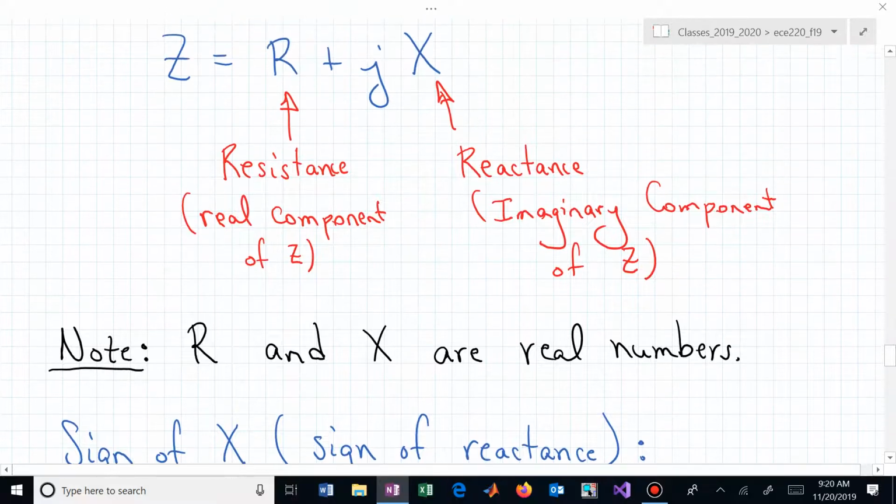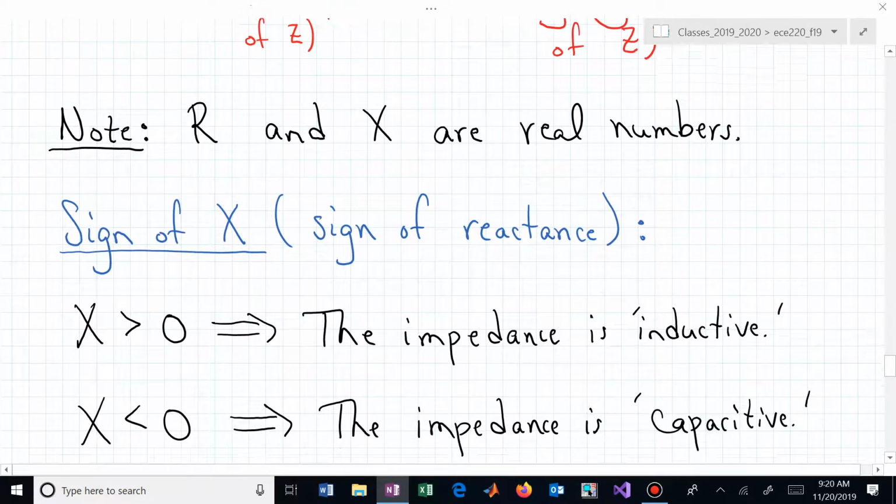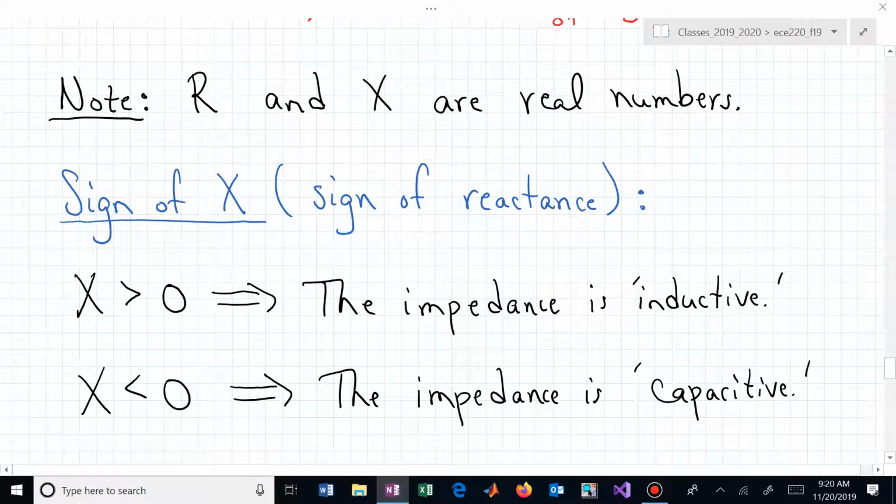And if we look at this impedance Z, we can determine what this box looks more like. Does it look more like an inductor, or does it look more like a capacitor in terms of its combination with the resistance? If our reactance is positive, remember we have j omega L, and that was in the numerator. That was the impedance of our inductor. That's a positive X. Our X is omega L.